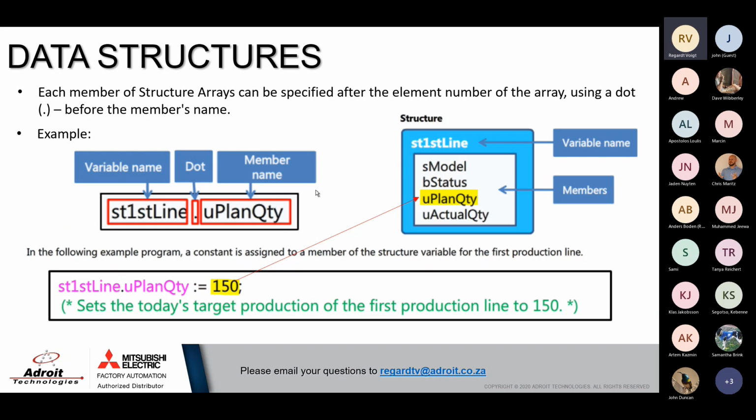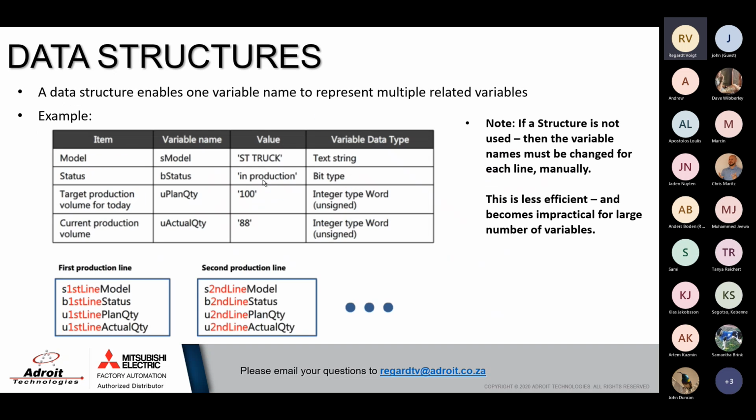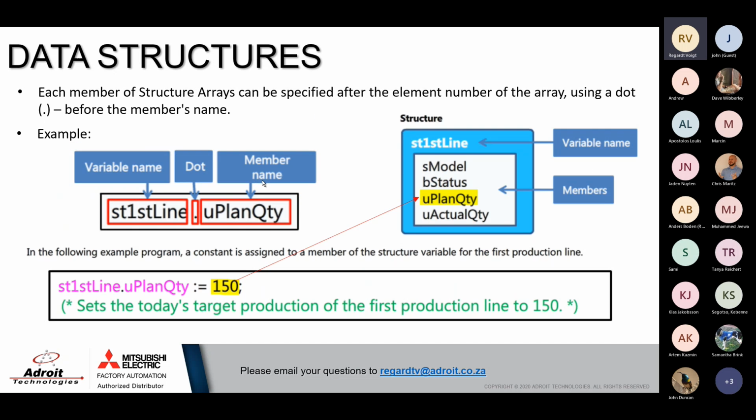The way to combine them would be to derive a user-defined function block and write the function block completely with your structured text, and use that in your ladder diagrams or in your function block program as an instance. But okay, that's a topic for a future webinar.